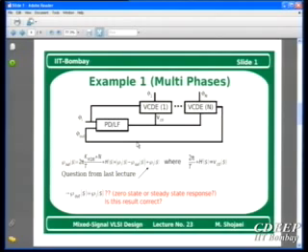Therefore, if we want to write the zero input response, it means phi_i is zero, where phi_i is actually a small signal. It means variation of phase is zero, but somehow VCTL is not the value that it should be. I have some VCTL which is not zero. Finally, because this VCTL again is a small signal, I have some deviation, but this should decay and come back to zero.